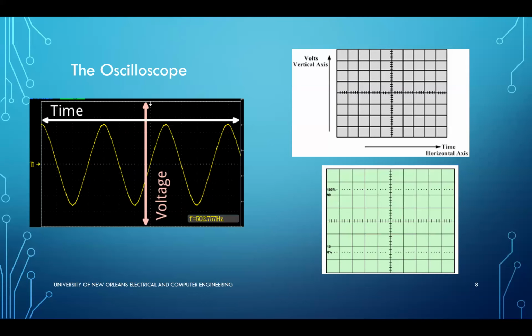If I change it to 2 volts, then I'll be able to see more, and so forth. So that's something you can adjust, right? How much each of those squares is worth on the x-axis and on the y-axis. In the same way, if I change the setup for the x-axis per division, let's say I have 1 second per division, then the maximum that I will see at any given point will be 1, 2, 3, 4, 5, 10 seconds of the signal, right?